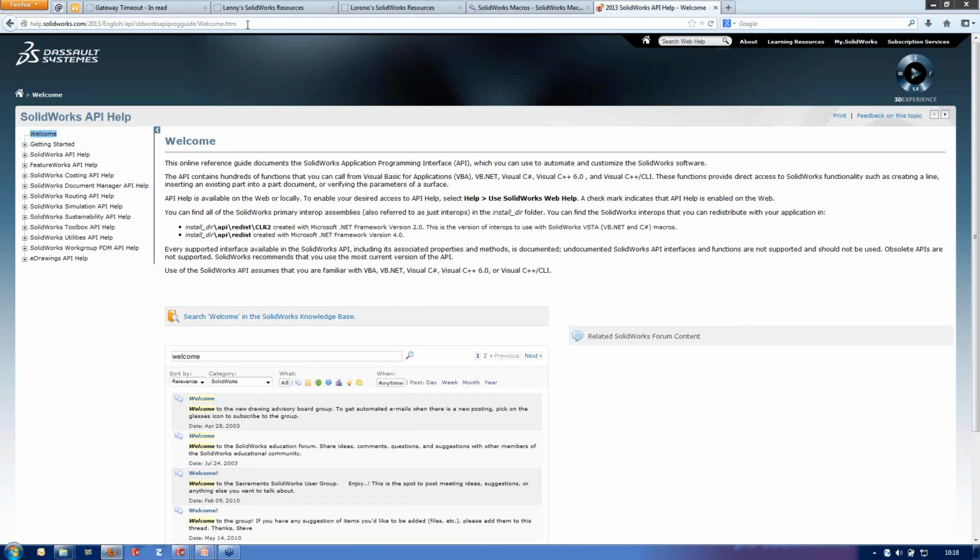All of the visible APIs are listed here. And it goes into great detail. You can search for them individually through this, but I would recommend using the search tool. That brings up a whole load of results, and you can dig through and find stuff out like that. The SolidWorks API, what's built in and what we look at and what I tend to do most of is all the VBA stuff, but it does also allow you to write the macros and the add-ins in both VB.NET and the Visual C family of code. But like I say, the easiest one and the one which it records the macros in is the VBA. So that's the one I talk about and the ones that what I do stuff in.